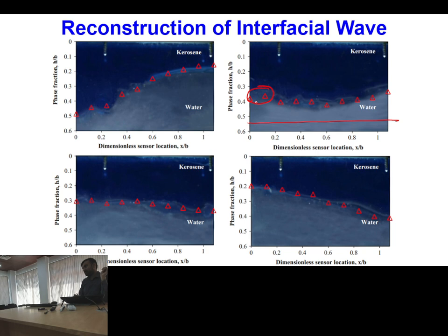which will lead to errors in measurement. So it means that if you have to employ this type of system, it will majorly be applicable to stratified flow regimes, and even in stratified flow regimes, good accuracy will be achieved when you have a planar interface. If the nature of the interface becomes three-dimensional, then because of the curvature effect in the third direction, you may have some sources of error.